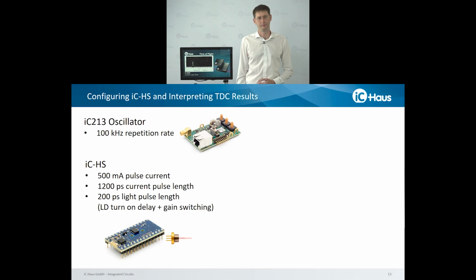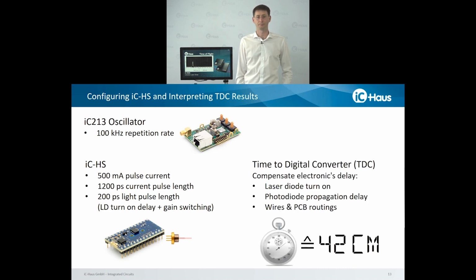This is not an electronic artifact. It's just the turn-on delay that the laser diode needs to put out light, get into its stable state, and then send out the gain switching pulse.